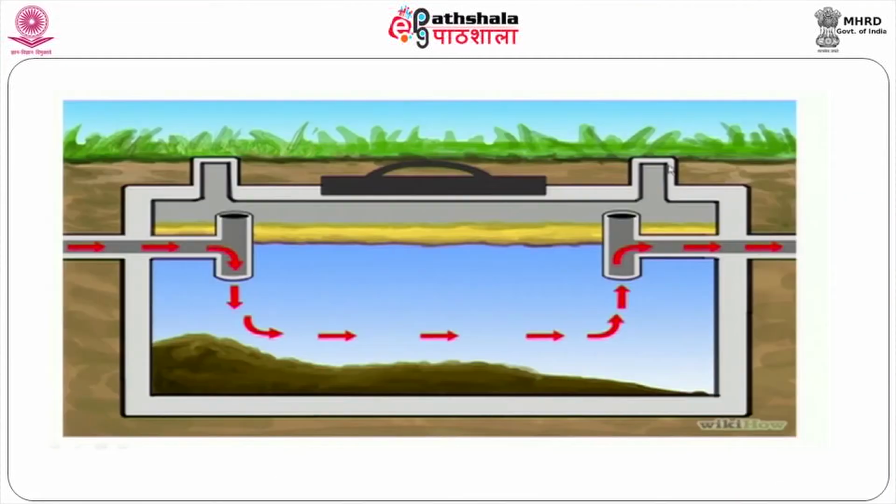Then finally, 2 different groups of methanogenic bacteria interact. One is hydrogen utilizing methanogens, and another is acetate utilizing methanogenic bacteria. Ultimately, the hydrogen as well as acetate are converted into methane, carbon dioxide and other gases. So, at the end of anaerobic activity, the organic matter fed in the reactor will be converted into carbon dioxide, methane, hydrogen sulfide and other gases. In order to relieve those gases, we have to provide a vent facility here.